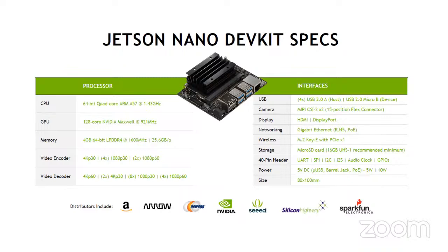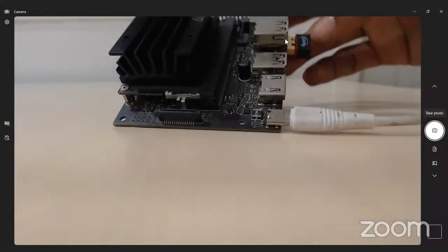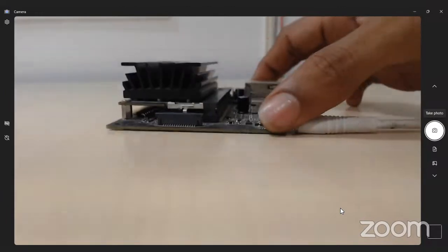To get that, you can use some kind of remote connection application. I'm using software called VNC, Virtual Network Computing. Using the VNC Viewer, I'm accessing the Jetson OS through my Windows OS. Then networking: there is no inbuilt Wi-Fi, so that's why we have to use USB Wi-Fi dongles to get connectivity. I'm using this Wi-Fi dongle here to connect to a Wi-Fi network.